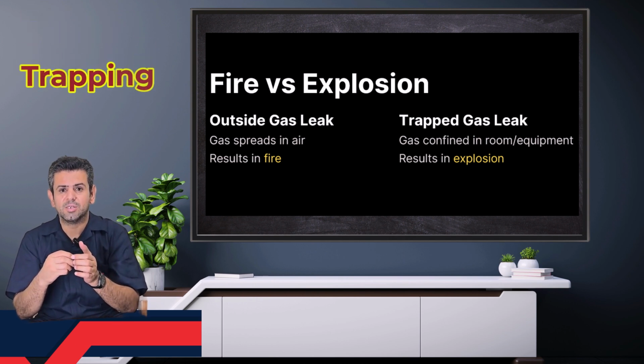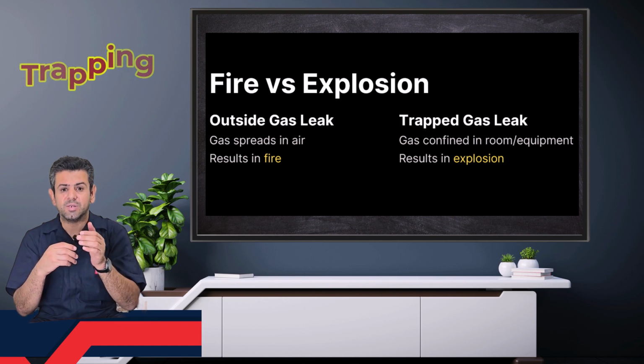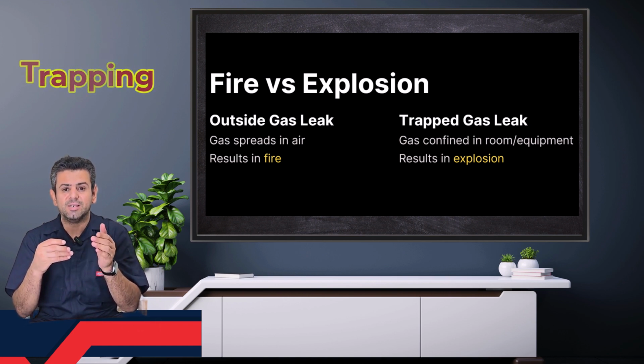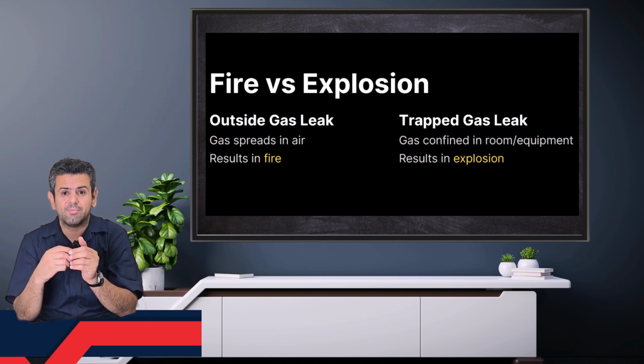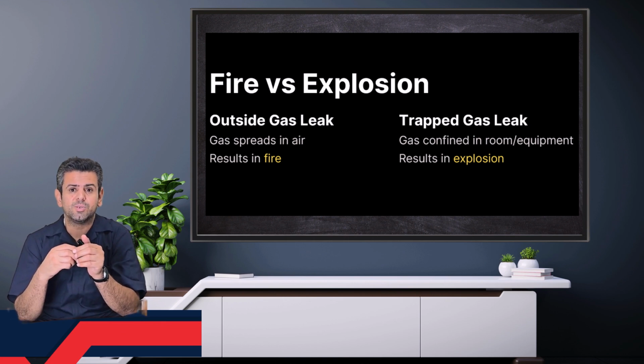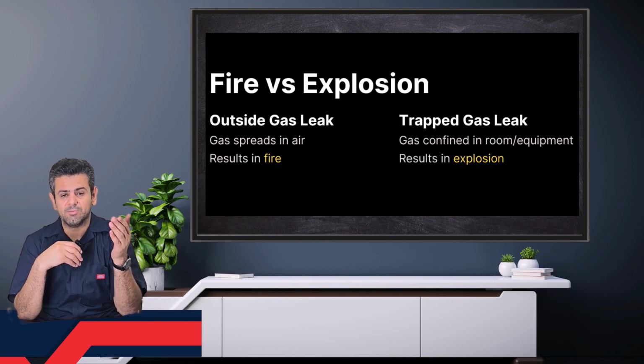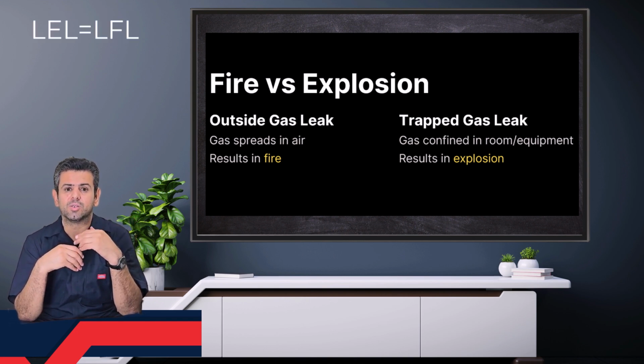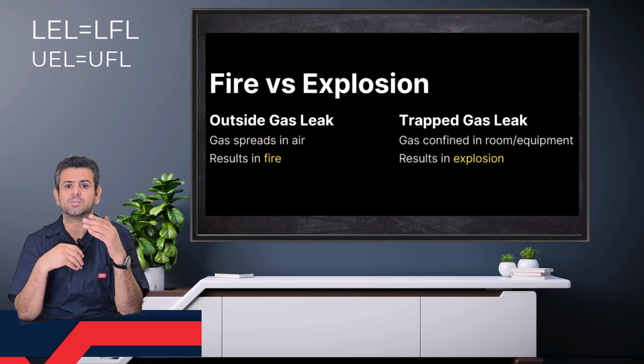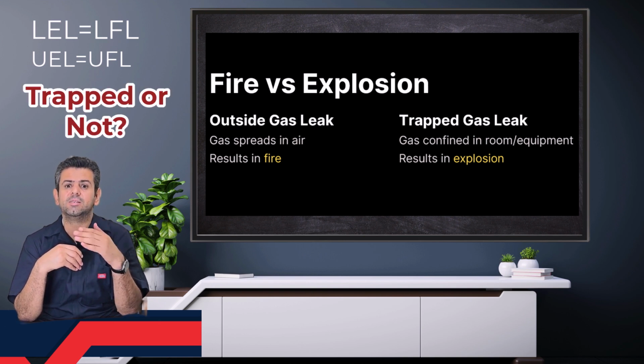Please pay attention: the key difference between catching fire or explosion is trapping. Trapped gas is a potential for explosion, and gas dispersion outside usually makes a fire. So remember, LEL equals LFL, UEL equals UFL, and they mean the same thing in different conditions, trapped